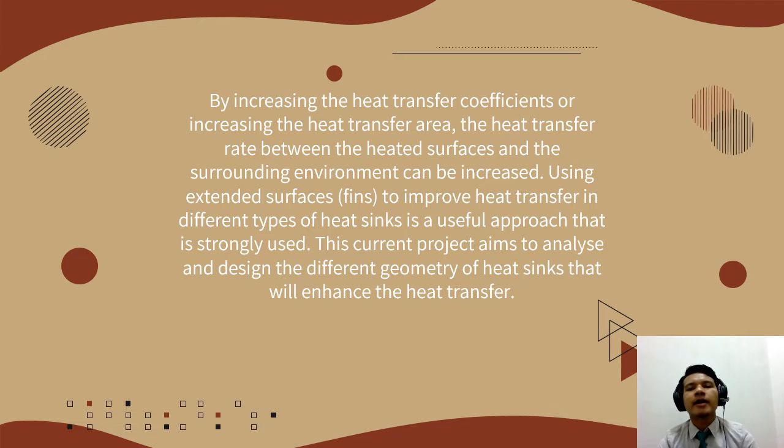From that, by increasing the heat transfer coefficients or increasing the heat transfer area, the heat transfer rate between heated surface and surrounding environment can be increased. Using extended surface fins to improve heat transfer in different types of heat sinks is a useful approach technique that is strongly used. This current project aims to analyze and design the different geometry of heat sinks that will enhance the heat transfer.